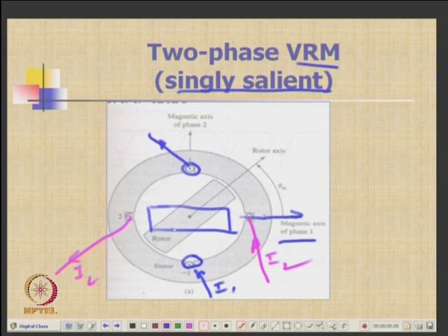There is a magnet which is lying here, right. So, there is a problem here. Do you conceive this? If it is totally symmetrical, the rotor is lying here. It has nowhere to go. If you excite the second one, it will experience equal torque on either side of the rotor bar, right. So, it has no way. If it is a little inclined in one direction, then it will go either this way or that way. It can go down or it can go up.